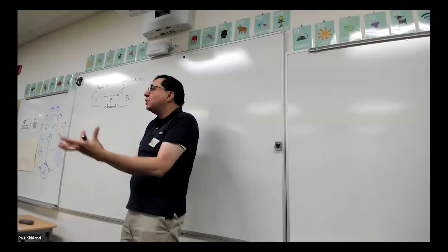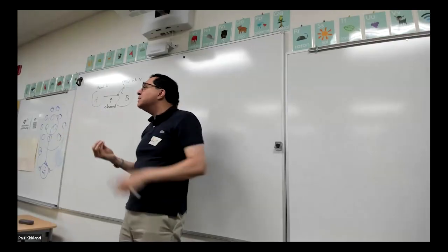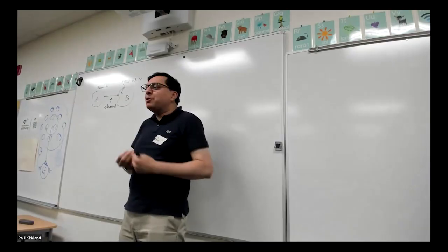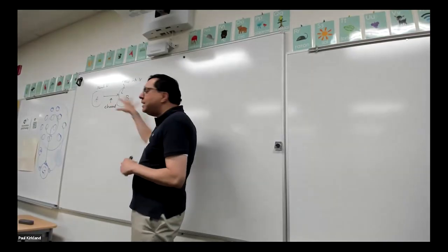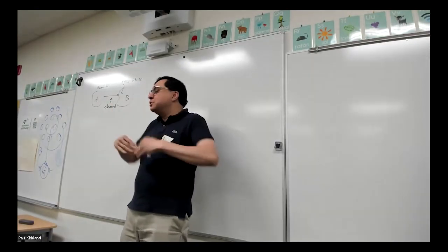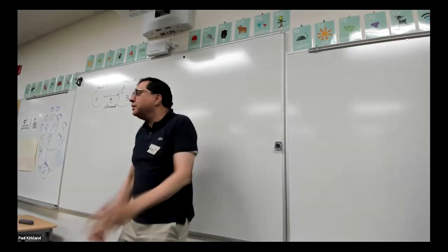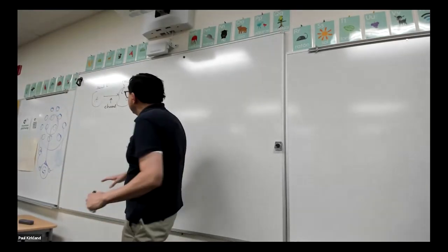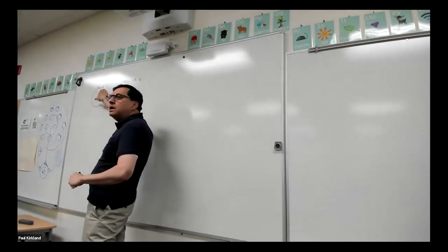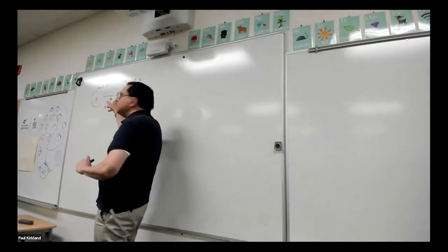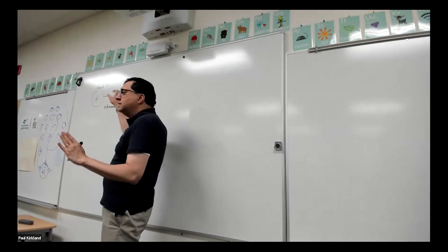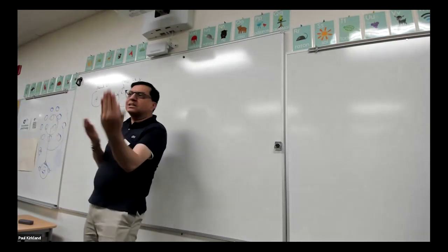And because that place has to hold a value, that means there has to be some circuit that implements state. Right? Makes sense. Now, in my hardware language, I don't want to allow the user to create all this extra circuitry without being aware of it. So the model we use here is that when I try to send a value, I have to wait until the receiver is ready. A send will block until the receiver is ready. A receiver will block until the sender is ready.